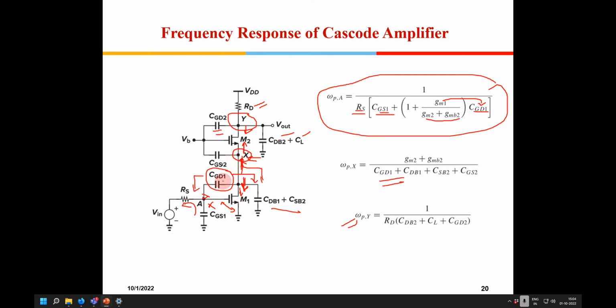I am going to remove this CGD, right? I am talking about X node, right? So when I am talking about CGS, I am going to put a voltage source there and remove CGD1. Then when I look from top to bottom, it will be only the drain to source voltage, and the gate voltage will be fixed there. Correct? But sir, normally when we create that small signal circuit, we are removing the DC sources, not the input AC sources.